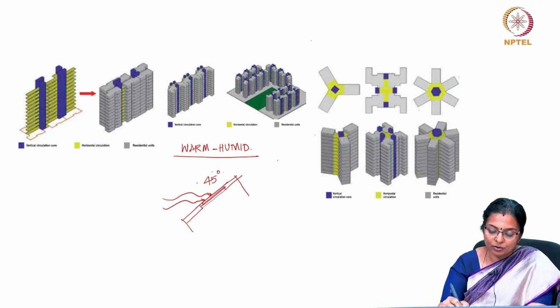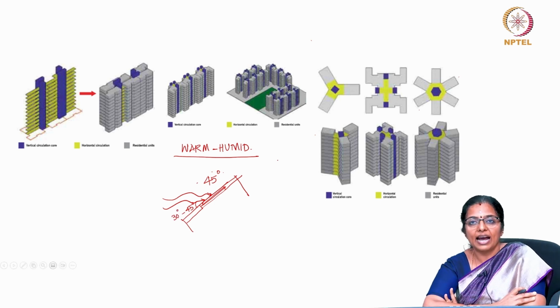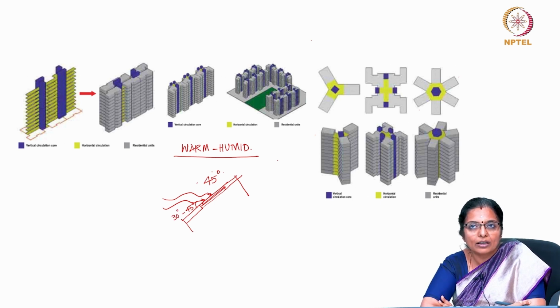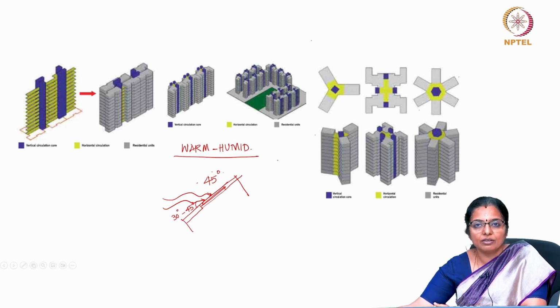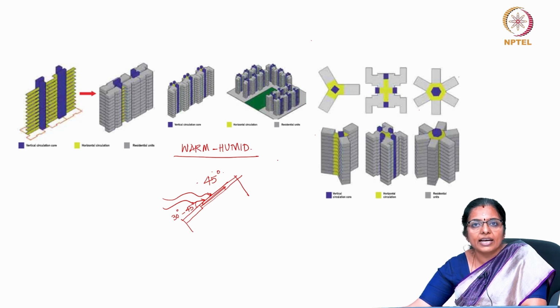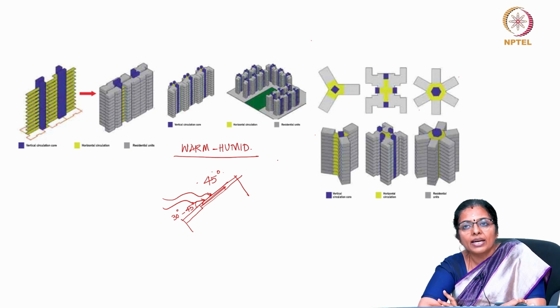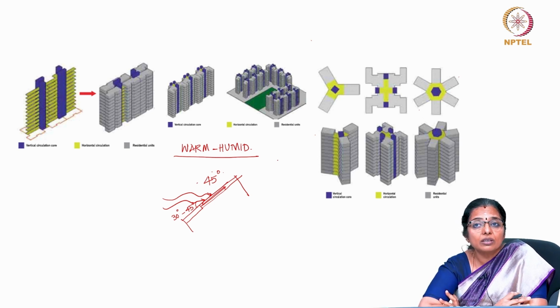So, you orient the room at 30 to 45 degrees angle if you want to bank on catching the prevailing breeze. Then the other criterion is that where a predominant wind direction can clearly be identified, the long side of the building should be arranged across that direction, because your main aim is to capture winds in a warm humid climate.